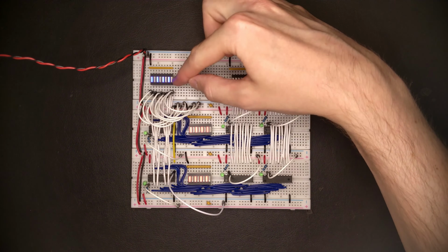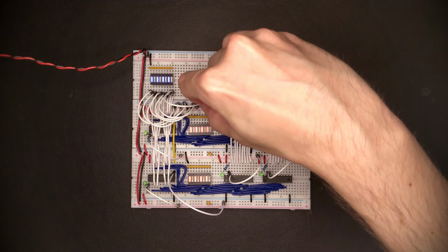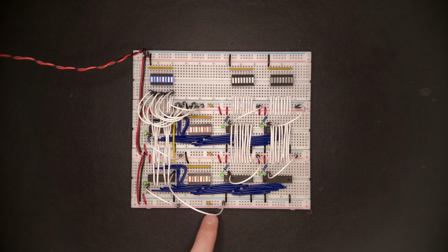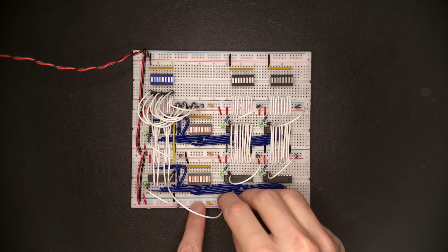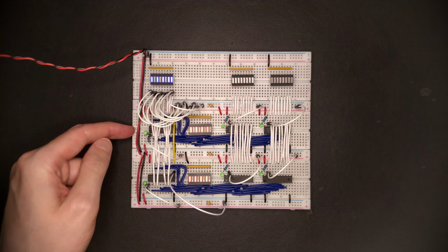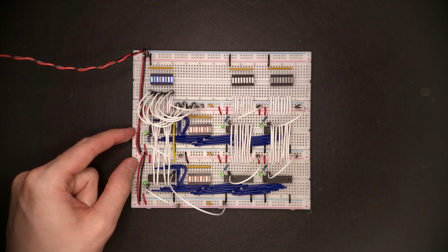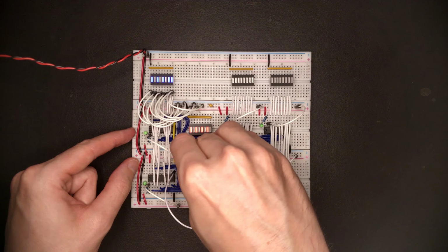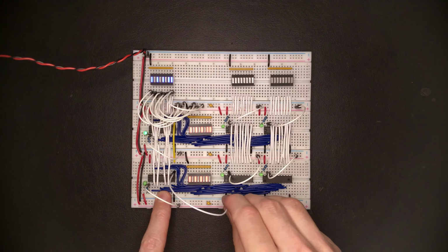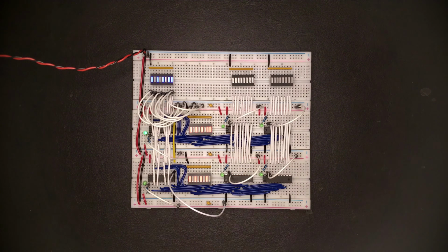But now let's actually change the least significant bit of the input. And now none of the registers is enabled for writing, so toggling the clock should not do anything. Which is correct, nothing happens. But now let's say we want to store this into the first register. So what we do is we enable that register for writing. And then when we toggle the clock, this stores the value into this register. And there you go.